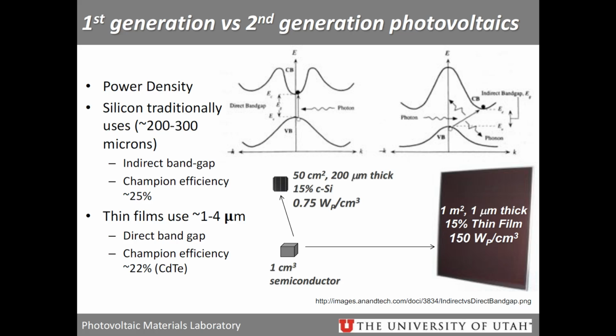So you typically need a greater amount of energy to transport the electron from the valence to the conduction band for electrical current generation, in essence compared to a direct band gap semiconductor. Now if we take these silicon structures and make them pretty thin, again, I'm not going into why this principle works, since this is probably outside the